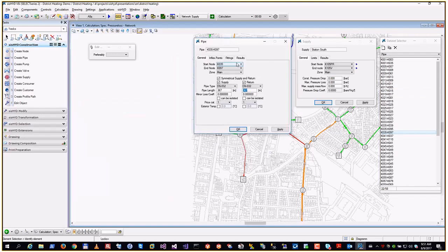Okay, with the dialog boxes, I explained we have with the right-click menu, you get a dialog box context menu. When you click here on empty space in the dialog box, you get the dialog box context menu. It allows to copy, delete, or create a new data set, and to navigate to the first in the list, previous, next. And there you also find the showing graphics. And for connectivity purposes, there is a function reverse connection, which means to switch the start and the end node.